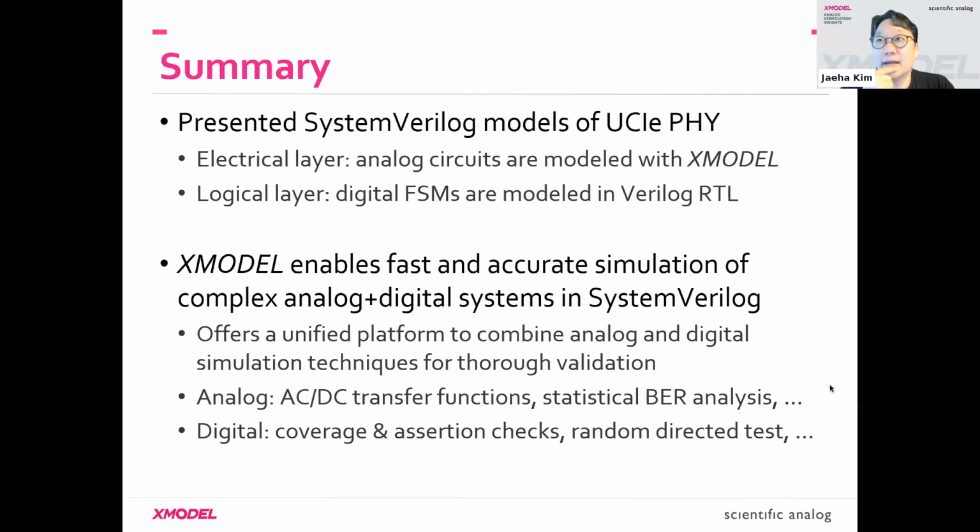Another non-ideality I can think of is noise. The phase interpolator can add jitter onto the input clock. That one is easy. There is any block that delays, let's say you can use the delay X bit or delay to clock primitive. Those primitives that can produce delay also have an additional parameter for adding phase noise or jitter. So by doing it, you can also add jitter. Let me know if that list is not enough.